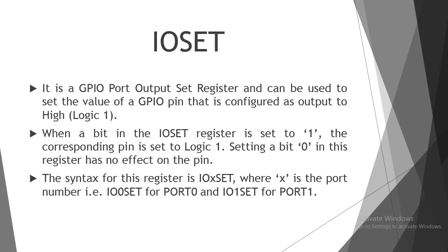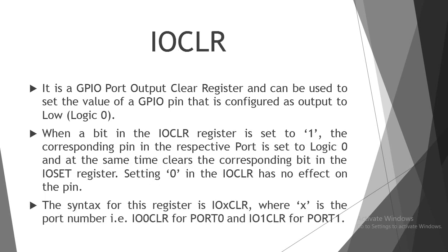The syntax for this register is IOX SET, where X is the port number. If we want to use port 0, then we have to write IO0 SET, and if we want to use port 1, then we have to write IO1 SET.